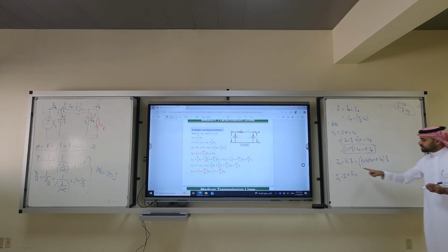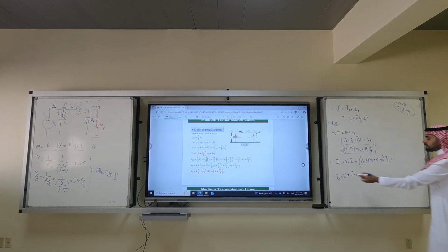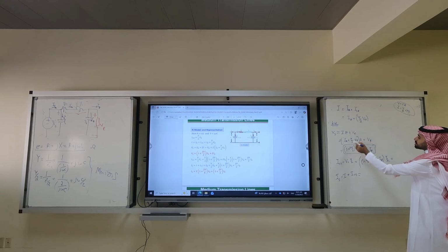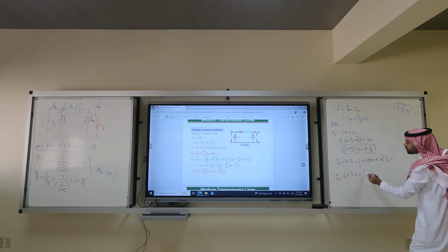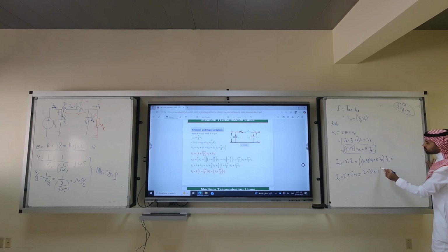So now ICS is a function of VR and IR only. Okay? You want to multiply by Y over 2? Let's keep it. So IS is I plus ICS. What is I? It's this quantity: IR plus Y over 2 VR, plus Y over 2 times (1 plus ZY over 2) VR plus ZY over 2 IR.